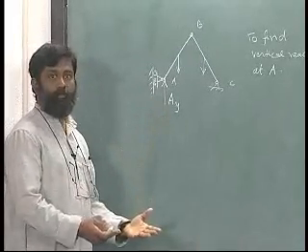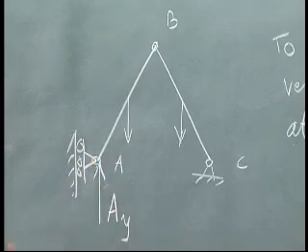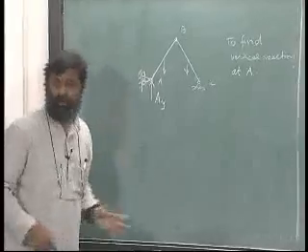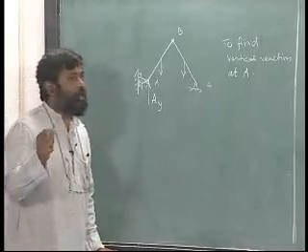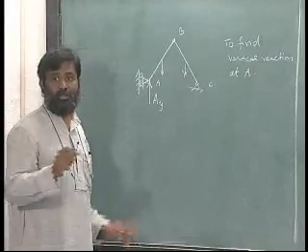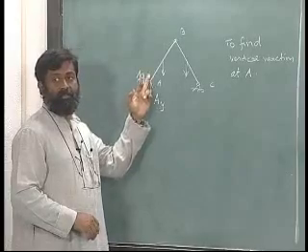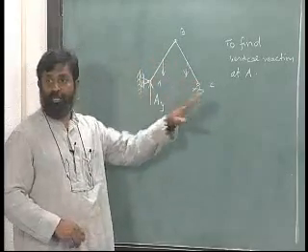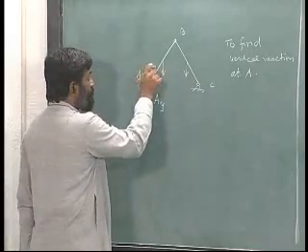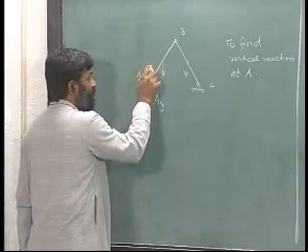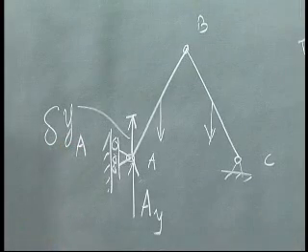I need now give a virtual displacement. Okay. It is not necessary I have to give a virtual displacement here, I can give virtual displacement at any point. Okay. This is a difficulty you will face, you can give it at any point, it does not matter, you will get the same equation of equilibrium. For now let me just give a vertical displacement here and find out the appropriate virtual displacements. So let me give a virtual displacement here, I am going to give a direction and this is delta y at A, alright.